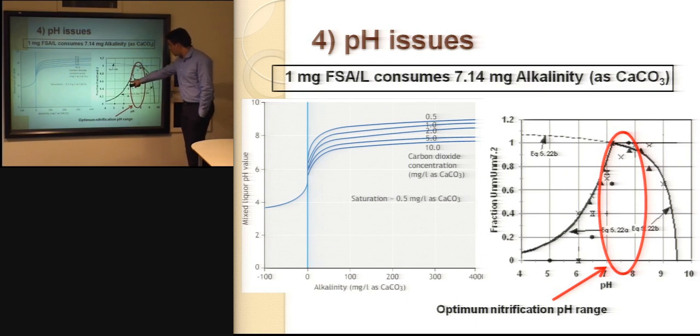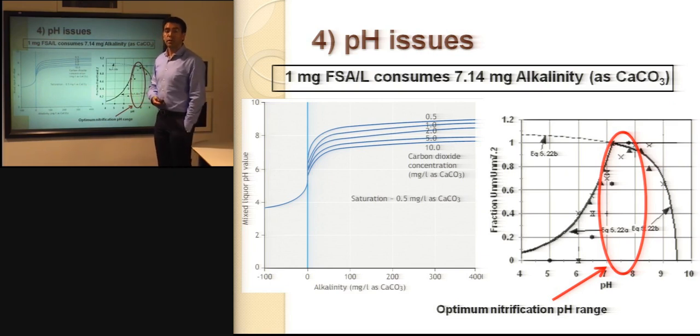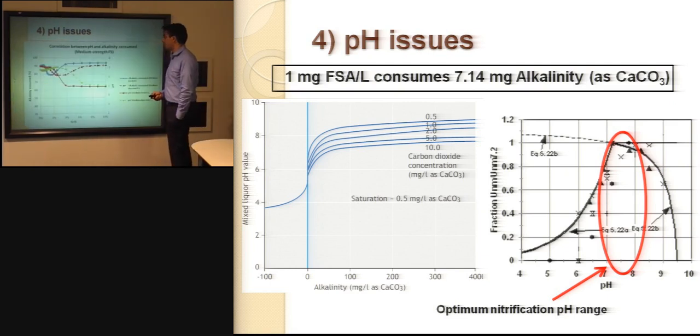That means that we will be able to oxidize only 60% of the ammonium that we have present. It can get even lower, around 40%, if the pH approaches 6. So if there is not enough alkalinity because of the high presence of ammonium, free and saline ammonia, in the fecal sludge, the likelihood to have a drop in pH can be very high.